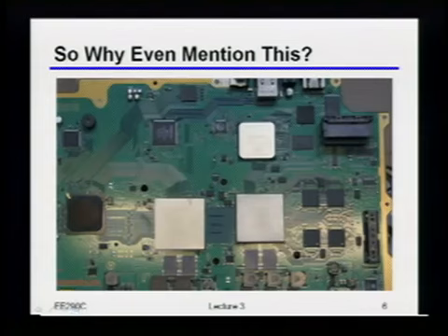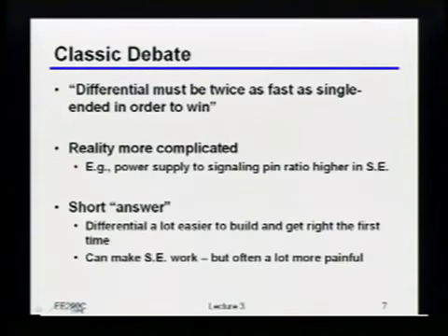And in fact, I think if you look even up into the latest and greatest high-speed DDR memories, or high-speed DRAMs for graphics processors, most of those are still actually single-ended. And they actually have very, very wide buses, something like 1,000-something pins just to get communication between the DRAM and that graphics processor. So what this is saying is that, yeah, single-ended is nasty, but it is still actually a very valid option in terms of trying to get things to work.